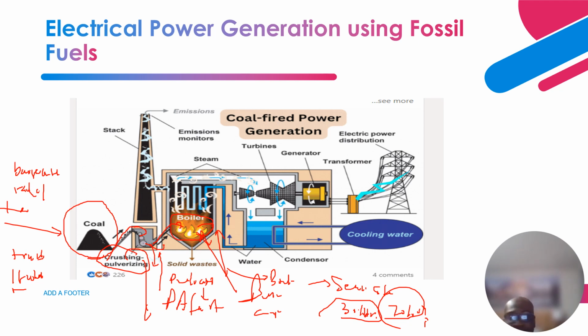That is part of our thermodynamics, right? Part of the thermodynamic cycle is to get the steam as dry as possible. But now you have 30% saturation and 70% dry steam. Even then, this 70% has to be dried further, right? So it goes through different stages, right?